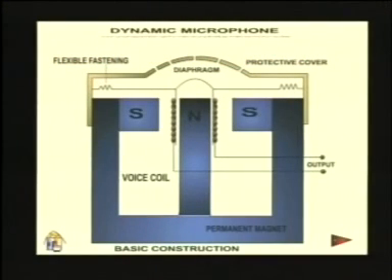Let us have a detailed discussion of the dynamic microphone. The dynamic microphone can also be called a permanent magnet moving coil microphone, PMMC microphone. The basic construction of this microphone goes in this way. Diaphragm. The line which is starting from here and making a bump here and then goes towards this side is known as the diaphragm. This diaphragm is a thin